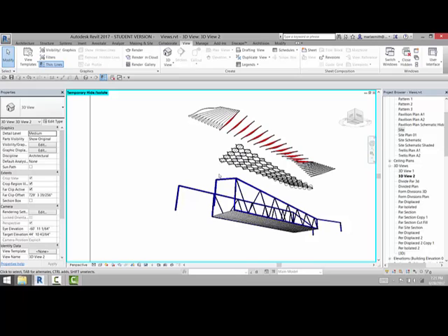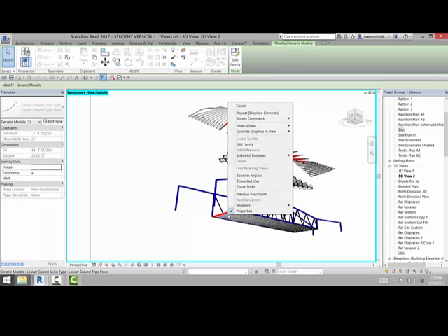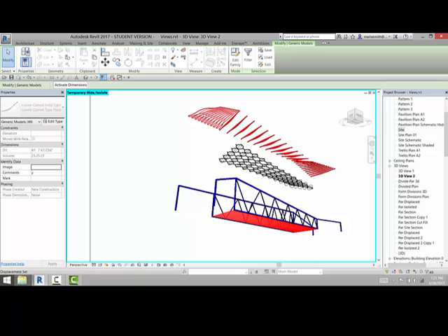All right, so the next thing I'm going to do is I'm going to displace this floor down, right? So I'm going to come in and select this guy, right-click on it, select all instances in entire project. And you don't have to create a selection set. Like you could, at this point, you could displace this whole thing and it will group it into a displacement group. So I'm going to do that this time.